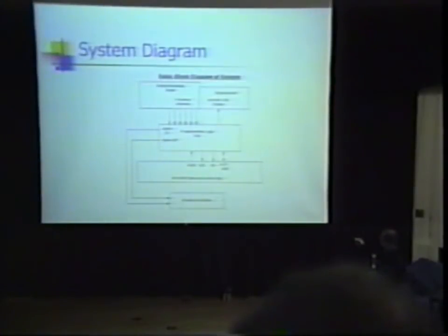The programmable logic chip will integrate the clock chip down here. It'll read the time from the clock chip and match it up with the alarms that are input from the user. Then it'll send 2 alarms on and off to the elevator controller.